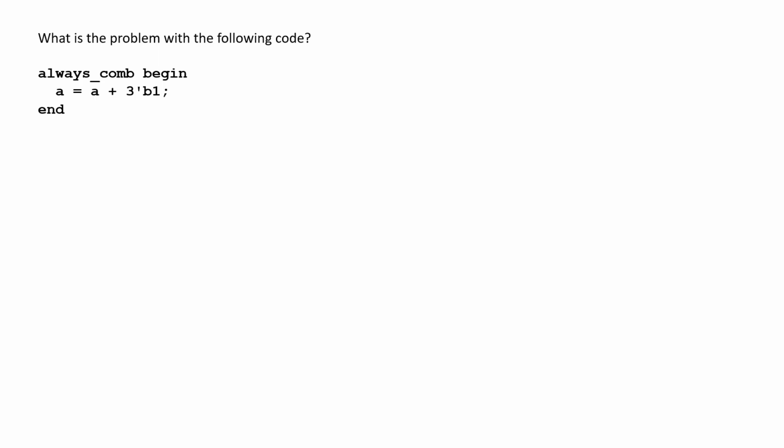So this will end up just incrementing. It'll become unstable, right? This will become a sequential logic circuit because it's cross-coupled basically. The output feeds directly back into the input without that flip-flop in there to control it, to make it only update every cycle, right? There's nothing that's controlling this. It's not clocked. I don't know, it would create like an oscillator probably. It would just run as fast as the propagation delay in the circuit would allow it to run.